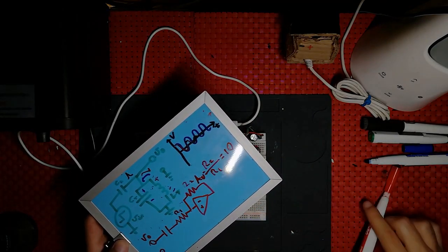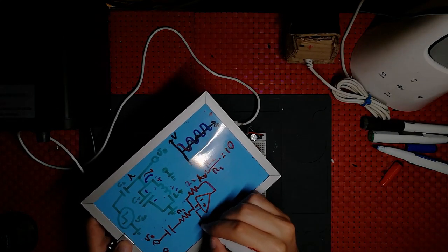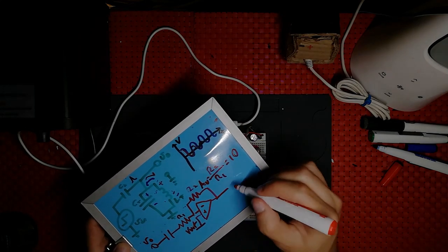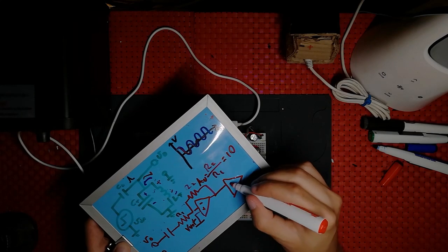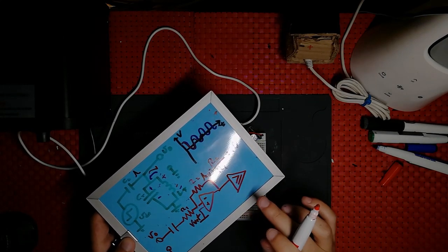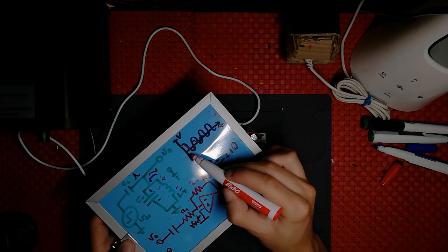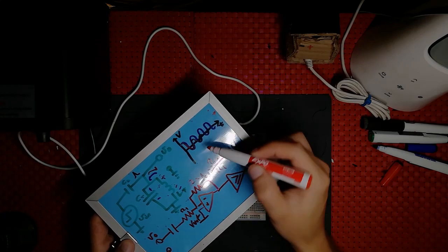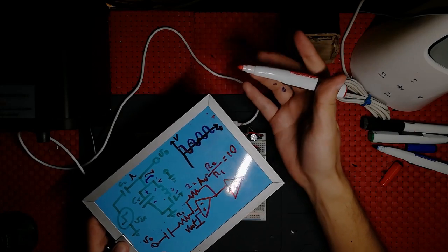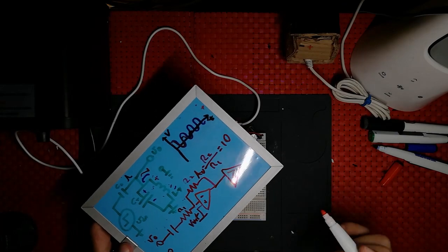The reason I'm amplifying it is because I'm going to use a comparator over here, and I need it to detect most of the sine wave components. So the bigger it is, the more probability I have to detect more, and the more precise the measurement can be made.